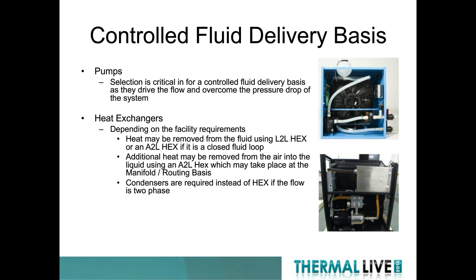The pump's critical because we have to drive the flow to overcome the overall pressure drop of the system. And the heat exchanger, in this case, depends on the facility requirements. If the facility has liquid that we have to transfer the heat to, we're using a liquid-to-liquid heat exchanger.